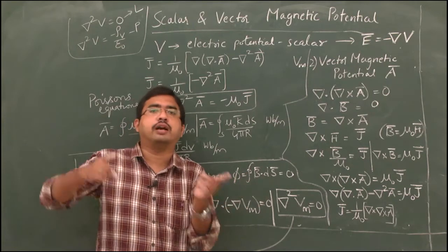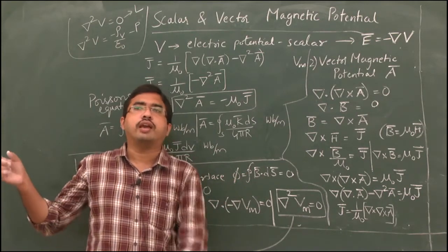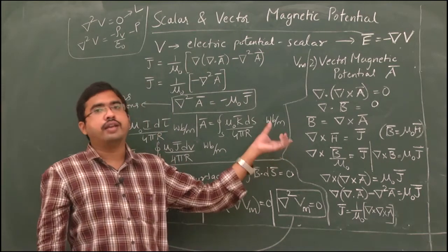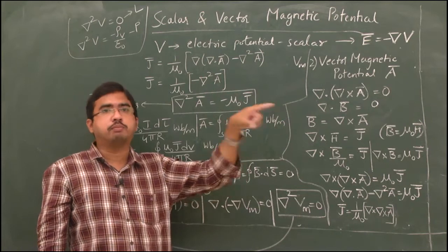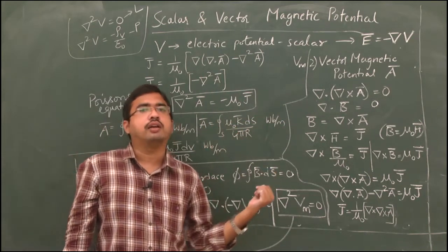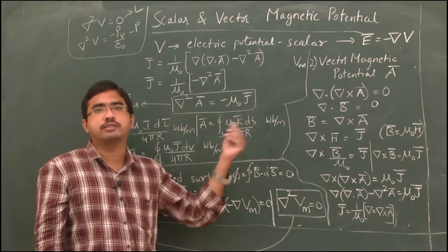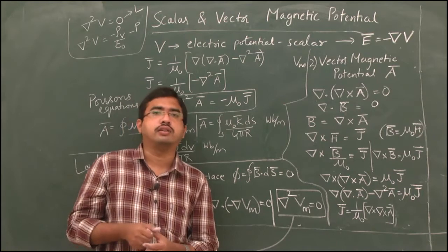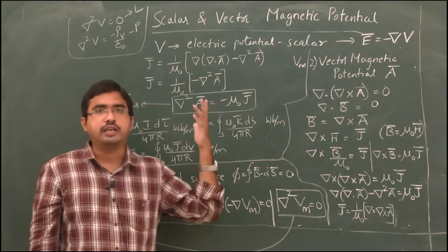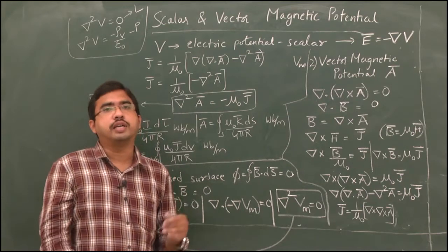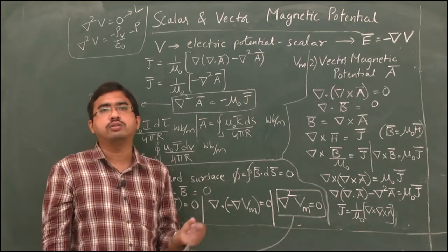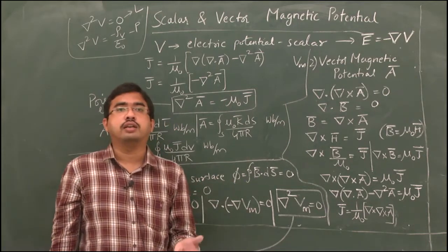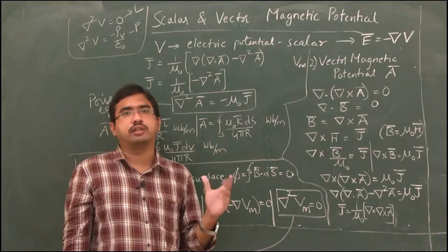Ampere's circuital law can be compared with Gauss law in first unit. Where you apply Gauss law, that surface is the Gaussian surface. Here where you apply Ampere's circuital law, that path is called the Amperian path. We have seen the proof for Ampere's circuital law also: integral H bar dot dl bar is equal to the current enclosed. After that we saw the applications: H bar due to infinite length of conductor, H bar due to infinite sheet of charge, and H bar in a coaxial cable, three derivations.